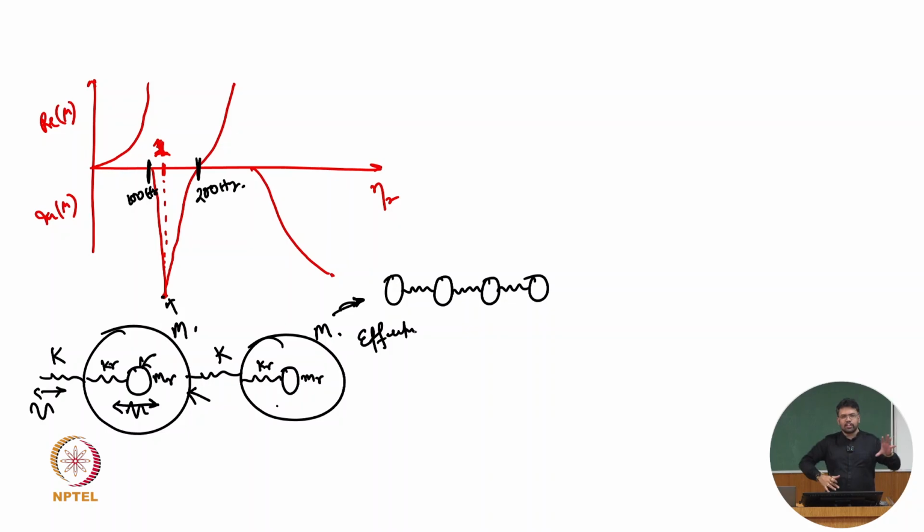Instead of solving that internal resonator, can we just solve a monoatomic chain and get similar behavior? Then what changes in the mass or stiffness do we have to make? So here we can call it ME and KE. The prime point here is how we are calculating the ME.